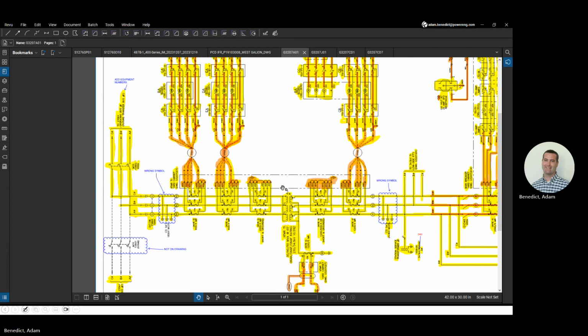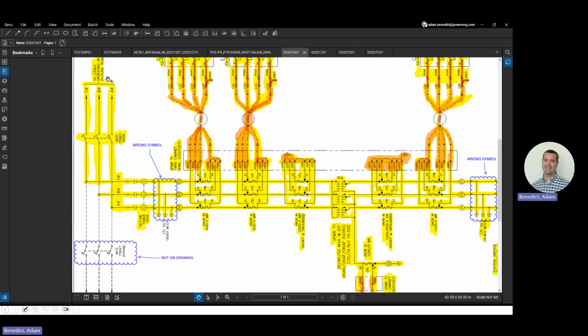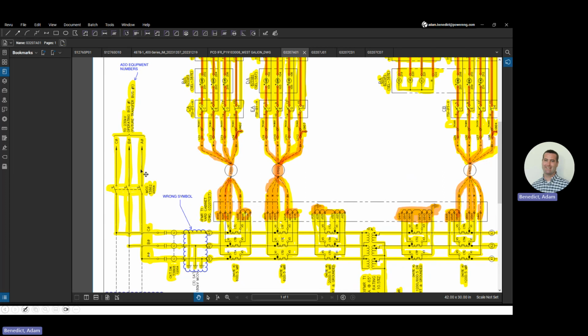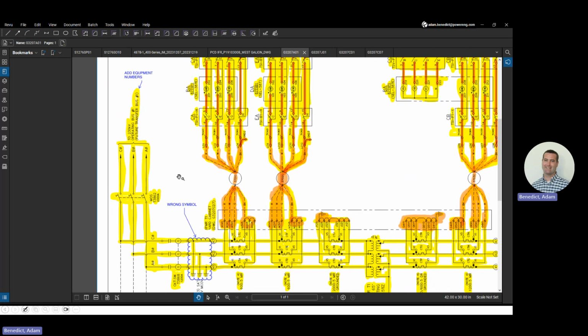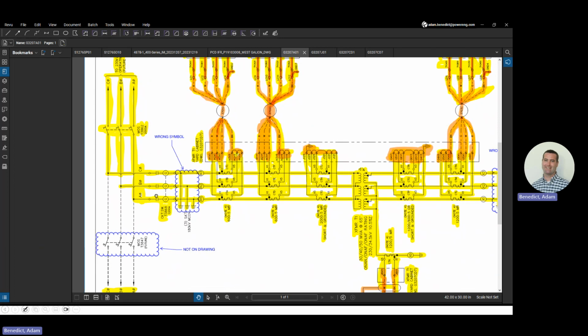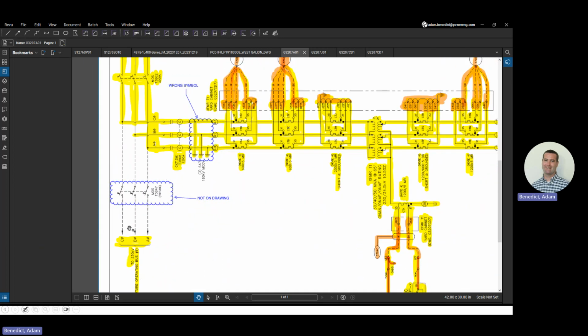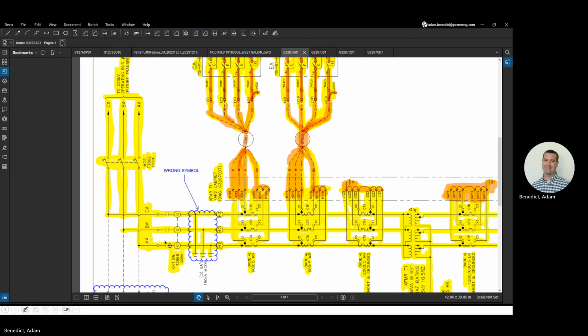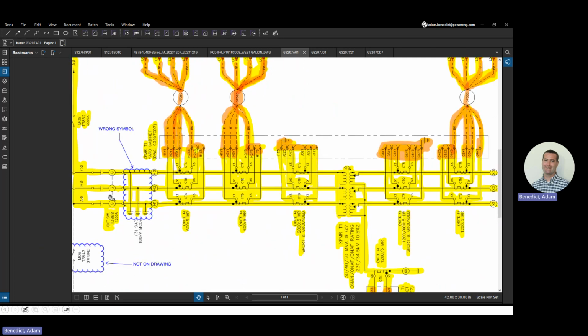All right, this is a different utility showing more the info that I like to see that you guys will probably see as well. Here we see there's our operating bus. Then we see our phases A, B, C with our switch shown in 3-phase configuration. They even show future equipment. Stepping down through, I want to make sure A is connected to A, B is B, C is C. And then we have our circuit switcher.